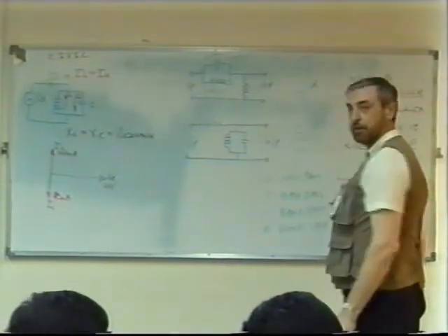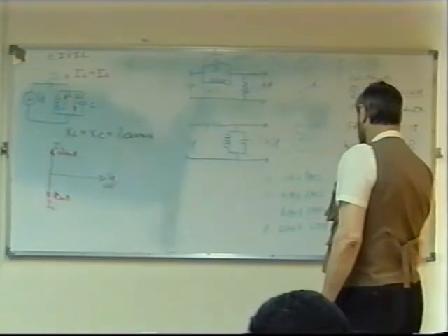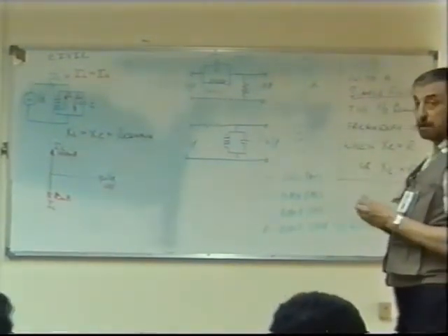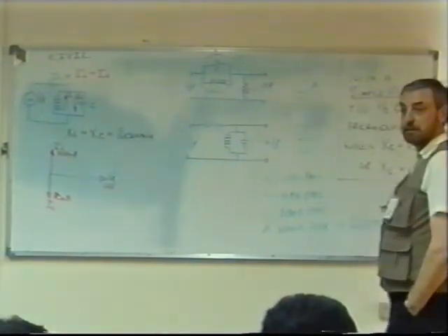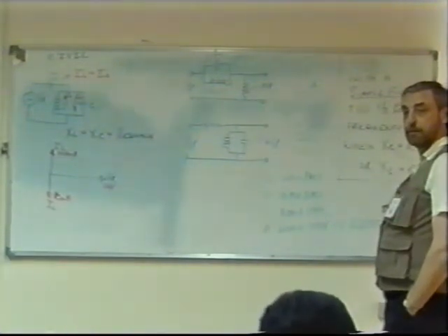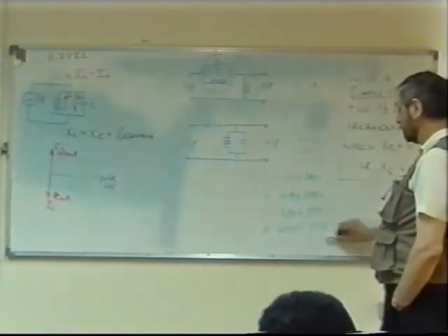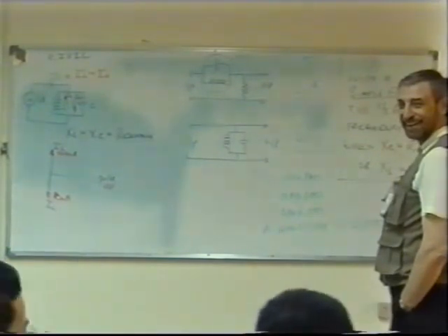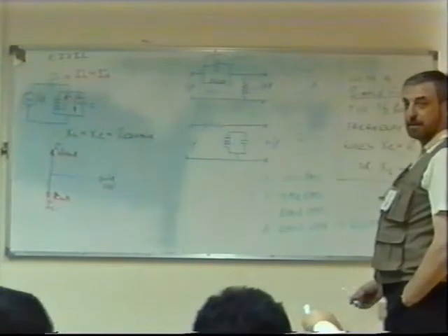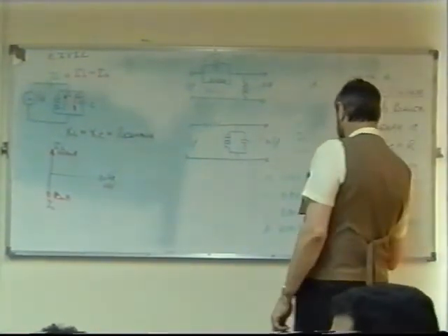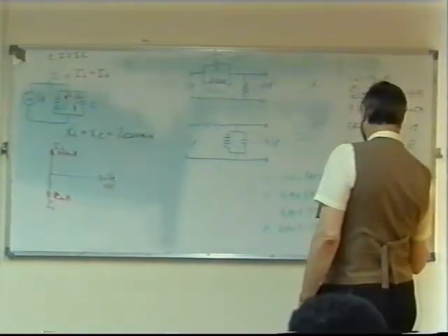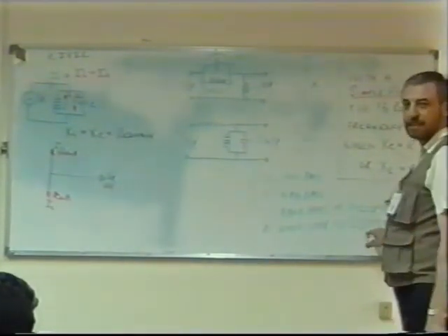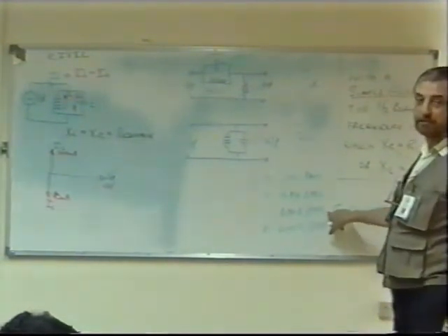Instead of D, they could have said rejector circuit. Remember I gave you two ways of describing this circuit: a band stop circuit or a rejector circuit. These two are the same, band stop or rejector circuit, but not this one. A band pass is an acceptor circuit. I didn't actually use that term, but yes, acceptor. This is less common, though. Rejector circuits are quite common. Usually you would just call it a band pass filter.